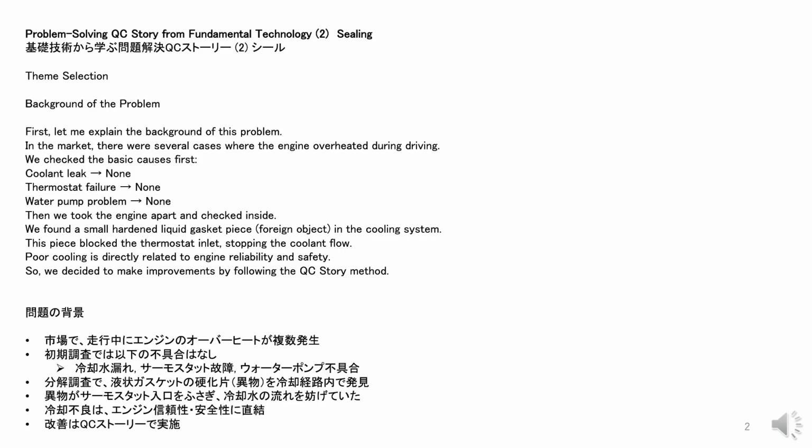Background of the problem. Hello. First, let me explain the background of this problem. In the market, there were several cases where the engine overheated during driving. We checked the basic causes first. Coolant leak: none. Thermostat failure: none. Water pump problem: none. Then we took the engine apart and checked inside.